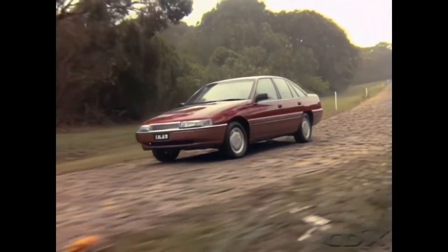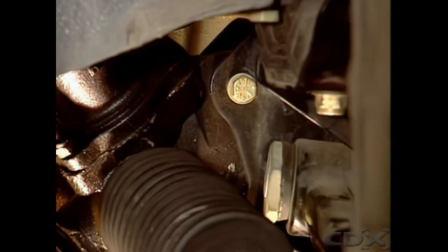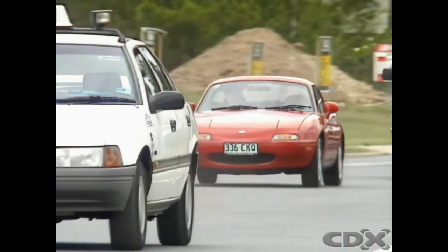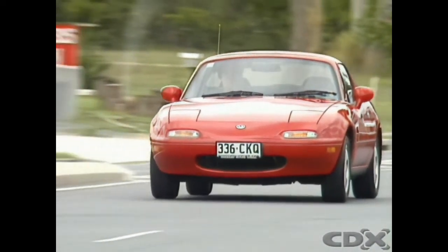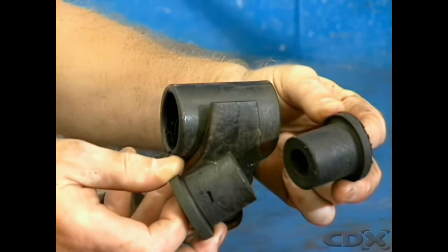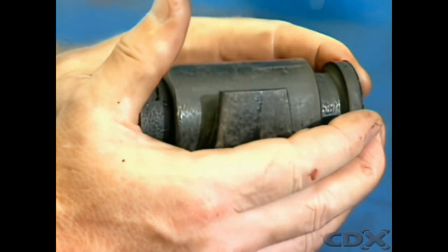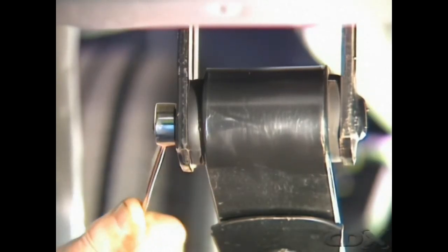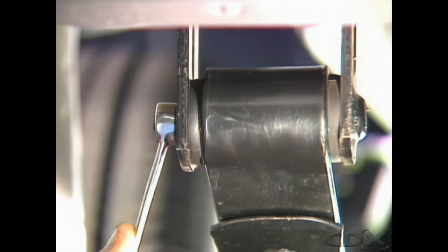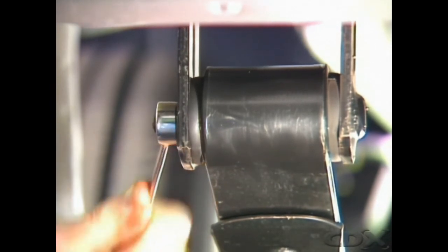Rubber bushings isolate noise and harshness, and dampen unwanted vibrations. Rubber bonded bushings can be used to mount the steering rack to the vehicle frame. The rubber absorbs small impacts from the suspension action, without transmitting them to the vehicle. Rubber requires no lubrication. Spring shackle bushings can be molded to form two halves, to fit into each side of the spring eye on the swinging shackle. With the spring loaded and the shackle plates tightened, the rubber is compressed in the eye and at the face of the plates. As the spring deflects, the rubber shears without tearing.